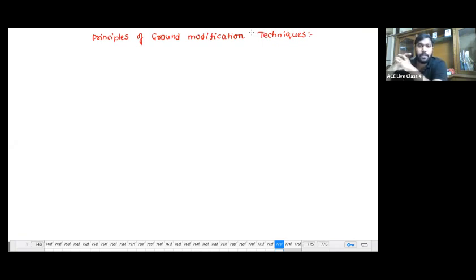Yes, well and good. But you are an engineer. You have to think not only of the design safety aspect, you have to think of the economical aspect also. If you go for the pile foundation, obviously to dig or drive the boreholes, to prepare the piles and install them, everything is a time-taking process, number one, which means it involves more labor. The more labor you involve, the more wages you have to give.